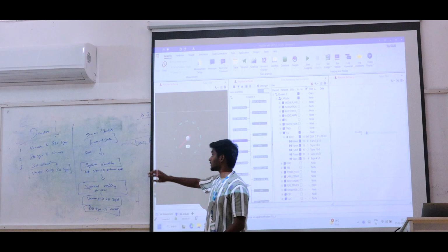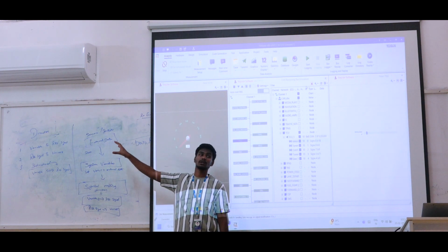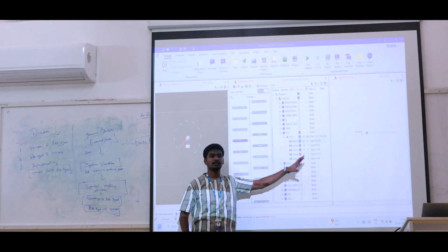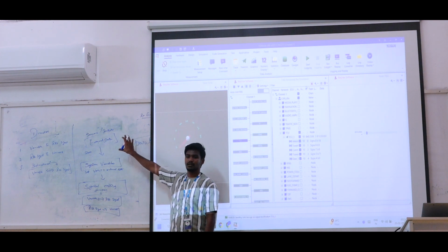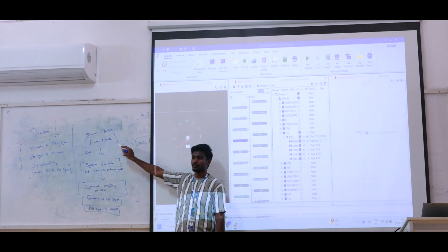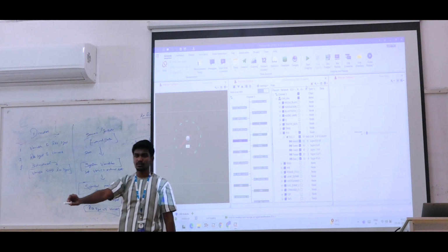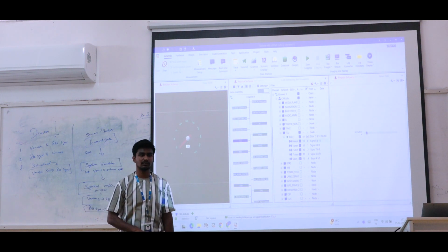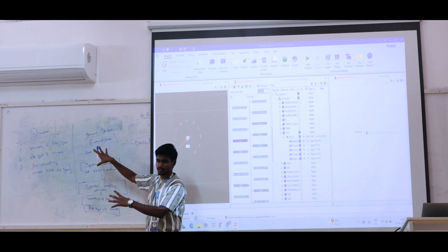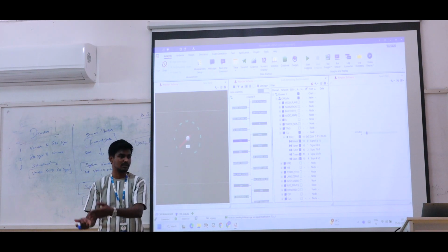Here also it is not like an ECU. It is like one source of data. We trigger some values manually, but instead of that we will get the real-time data. That is what I mentioned here. It does not come from a real-time ECU. This Arduino is not a real-time ECU. Now we can assume for this RBS the system variable concept only I mentioned. This Arduino CAN MCP will send us raw message values.